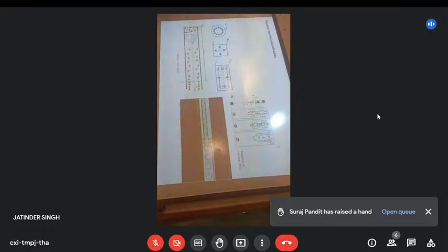There's a whole range of particle focusing methods that are passive as well, which either use the fluidic properties, Newtonian or non-Newtonian fluid, or channel geometries to go one way or another. Here you can see depending on the channel geometries, there's a number of different focusing points for particles because of the inertial forces and the lift forces imposed by the walls.